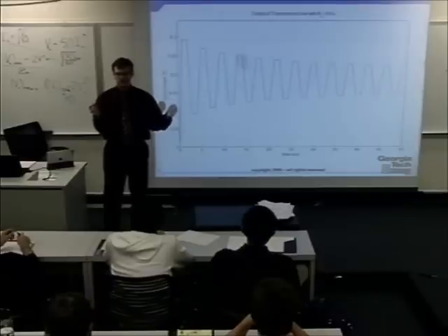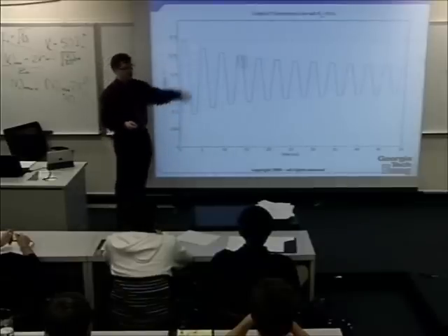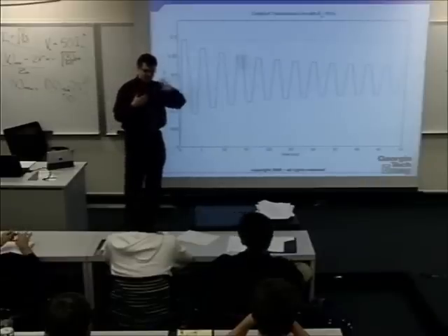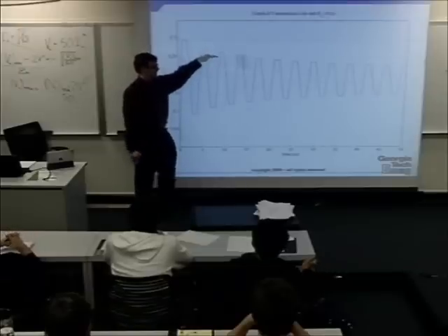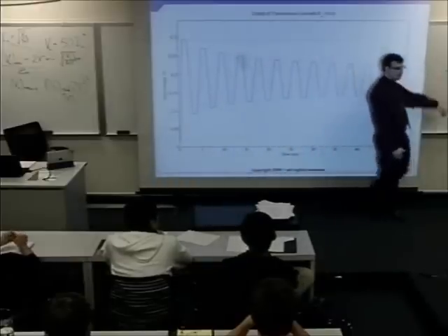It's oscillatory. Whereas with the previous resistance, when I had 20 ohms of source resistance, the wave would go down, bounce back and forth, and then damp to a single point. In this case, it's actually damping into a two-mode solution. It's now oscillating between 2 points, and it will do that forever.